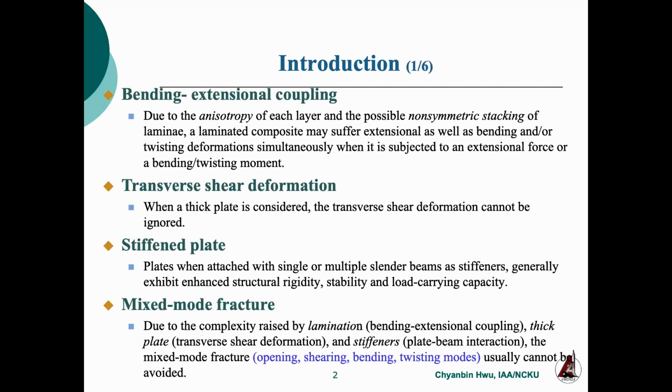For the laminate plates, due to the anisotropy of each layer and the possible non-symmetric stacking of the lamina, usually the bending extensional coupling cannot be avoided. And if you think the plate is a thick plate, the transverse shear deformation cannot be ignored. And if you consider further the stiffened plates, the plates attached with a single or multiple beams, generally the structural rigidity, stability and load carrying capacity can be enhanced.